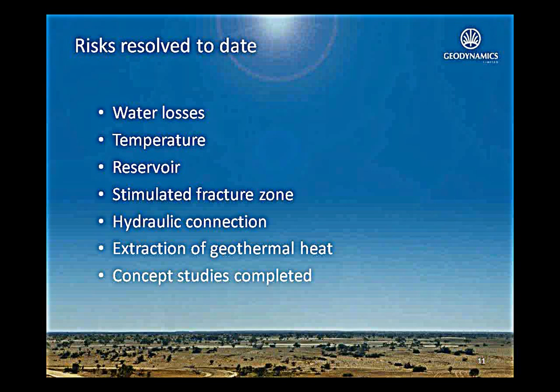We've demonstrated at Habanero that we've got a reservoir there. We've stimulated that reservoir. We've enhanced it and made it bigger by drilling multiple wells into it, and achieved hydraulic connection between wells, so that what goes in one comes out the other and vice versa. There is hydraulic connection within the reservoir.